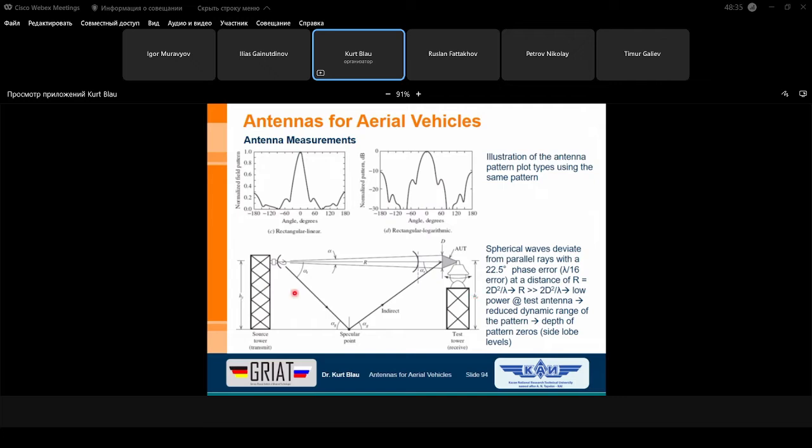In earlier years, these towers were made from non-reflective material, for instance dry timber or dry wooden material or plastic material with a small permittivity, so that around the antenna under test we have no reflections, and also we have no additional reflections from our illumination